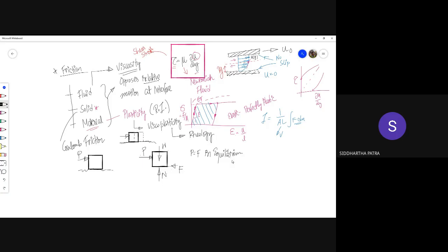But all this while, friction was simply leveling it up to balance whatever external force you are applying. So it simply can change. And as we discussed earlier, a frictional support is as good as a pin joint, because there are two unknown forces, both N and F are unknown. But one thing is known about F, that the limiting value of F is mu s times N.